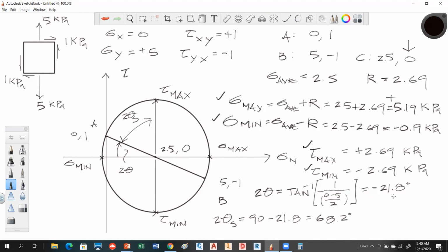And this angle, and remember you have to divide this by 2, right? Because these angles are double what they should be. This angle then is the angle along which this occurs. So you're really looking for 4 things, okay? You're looking for min and max, you could consider that 1 and that 2, and then there's your 2 angles, all right?